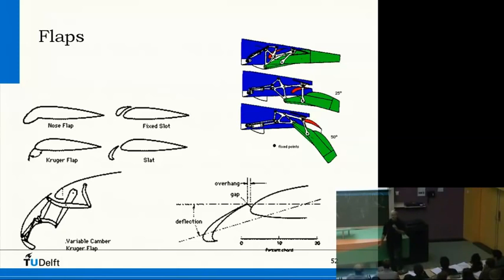If you extend the flaps, you have very high velocities on the upper surface, but you fly at very low speed, right? So there's no critical Mach number involved there. If you would do that at cruise, then suddenly you would have very high drag, and then you would need a lot of fuel.